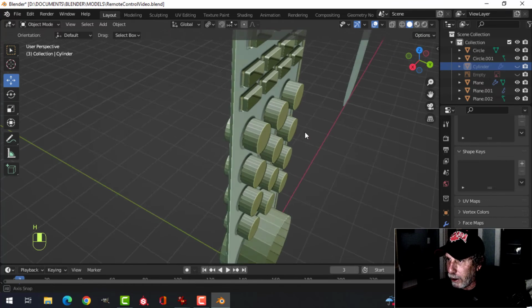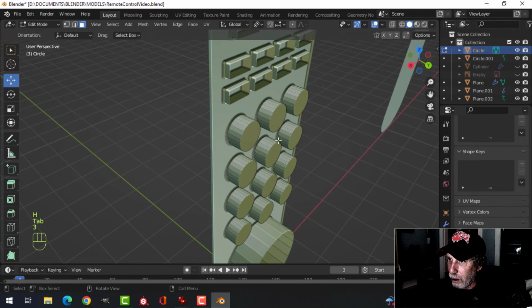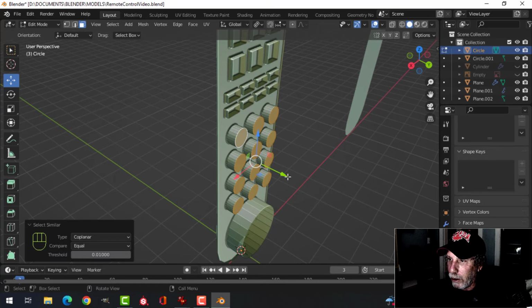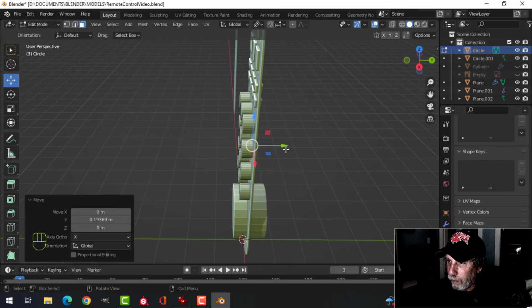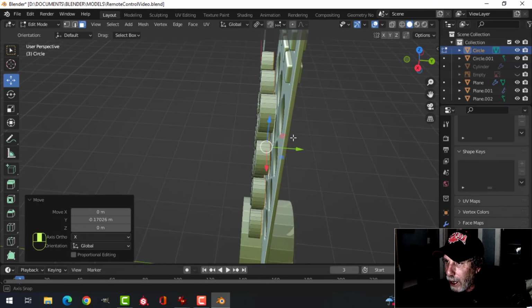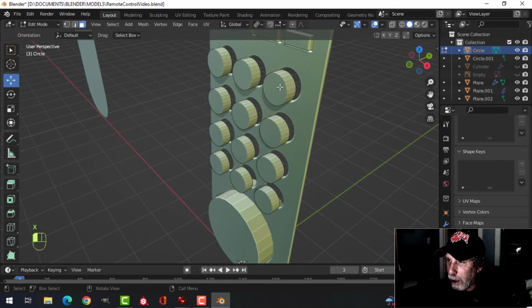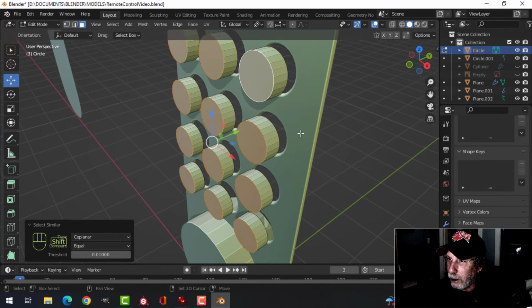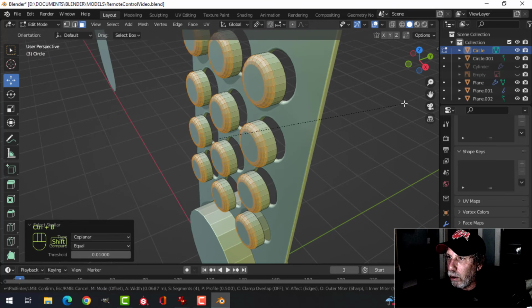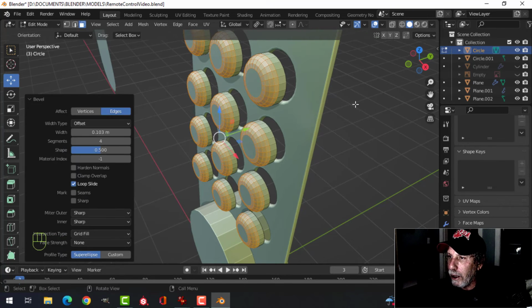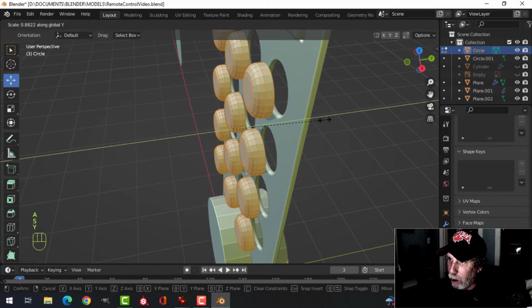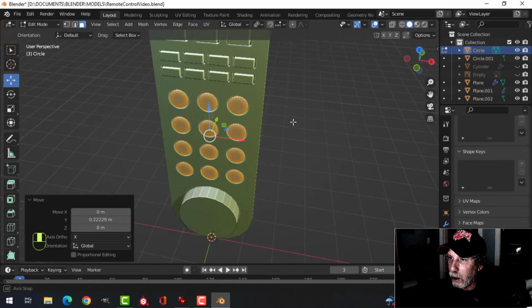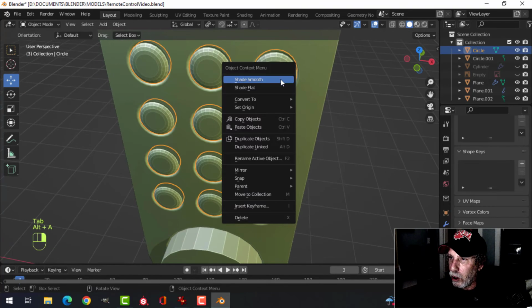All right, let's do these guys now. I'm going to actually hide the back. Come in here, select that. In fact, why not try this? Similar coplanar. I'm going to pull them through. In fact, I'm going to pull them like that. I'm going to get rid of that face right now. Select this. Oh boy. Let's do this. Coplanar. How about that? Control B to bevel, pull, have a bunch of segments like that. Select them all, maybe scale them in the Y a bit, pull them into place like this, and let's shade smooth.